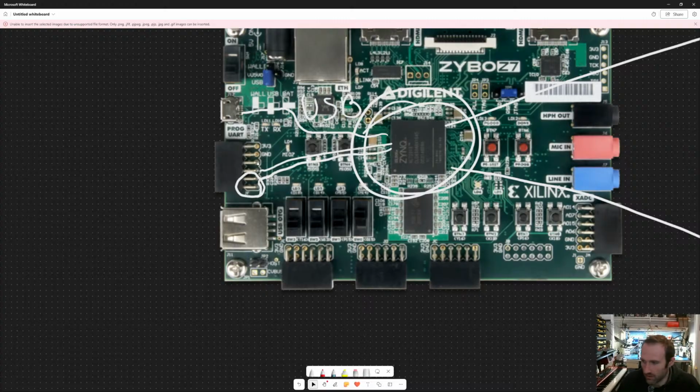The weird thing about this though, is if you watched last stream, I was able to pick up some data. It just seemed delayed. And what I think that actually is, is crosstalk happening between this signal and this signal when I was getting the data. As a reminder, I had these two looped back with a jumper wire connecting these two.